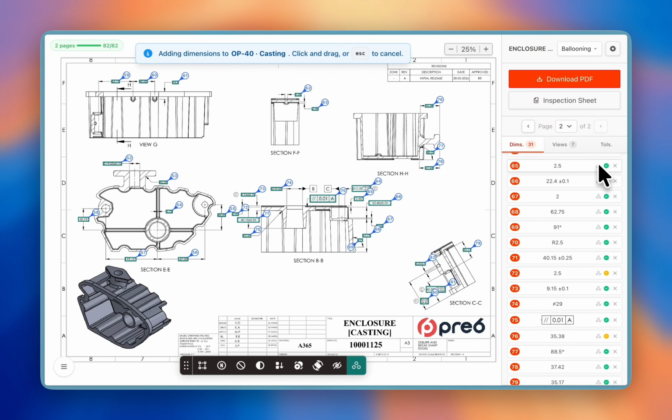You will share some of your recent 5 to 10 PFMEA and control plan documents with them and ask them to go through it. Learn the kind of operations we have, the kind of failure modes we have for certain features that we achieve through that operations, the severity value, how many times it has happened, that is the occurrence value, all of that, and refer to that or use that going forward for developing any PFMEA or control plan. We go with the same analogy. We have an option here called FMEA library and control plan library.